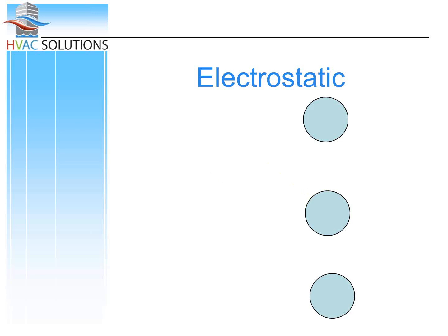So depth loading is the exact opposite, and it starts collecting all the way at the back end by the furnace, and then uses the entire filter to capture and hold particulate and dust. If you've ever seen filters that have combs in them, this is why, because they catch so much stuff that without those combs, the filter would collapse.